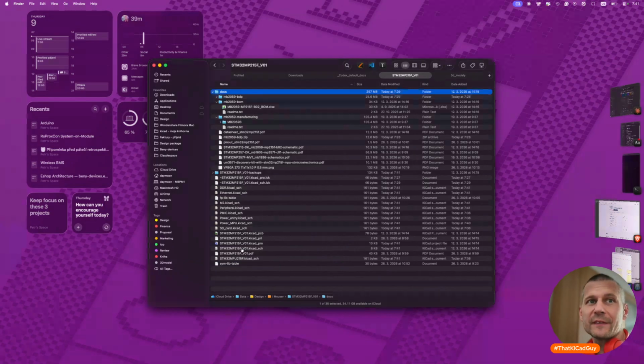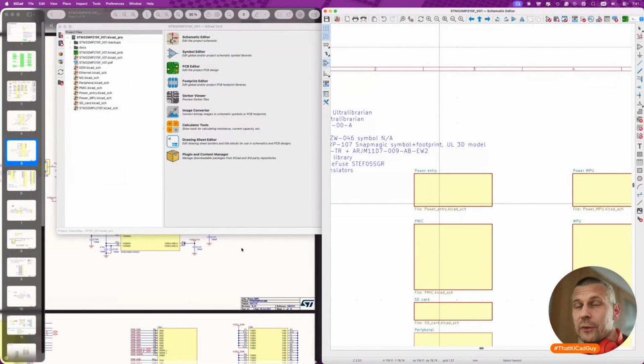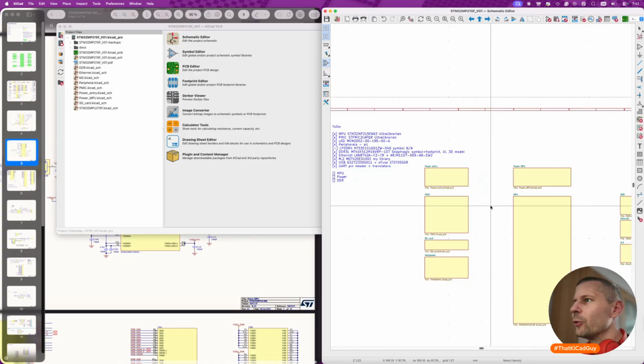the blocks with some symbols, some schematics, be careful because sometimes KiCad can. Yeah, I think everything is under control of you, but sometimes you hit yes or agree, and then KiCad reinitiates the schematic block or creates a new one and deletes the old one. I don't know. It happened to me a few times, and since then I am very careful what I'm doing. And